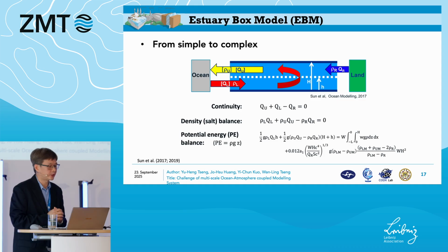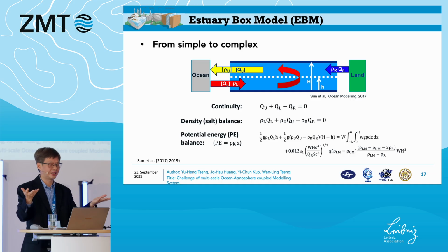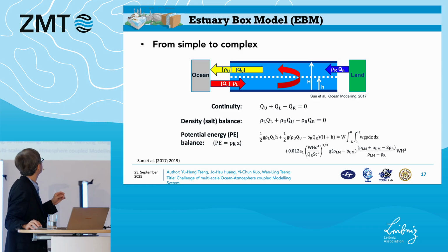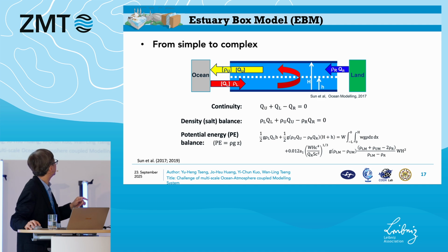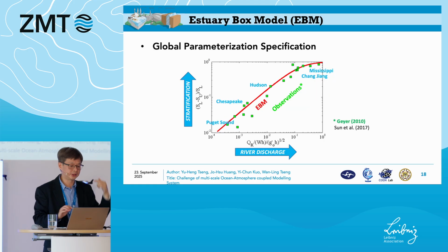So just quickly, a little bit about the estuary box model. We are trying to parameterize, but this parameterization is based on some physics. We consider the continuity equations, the density balance, the potential energy balance, and also the momentum balance within that, so that we can consider the estuary exchange. The open ocean water can move into the land, and the river runoff from the upper layer can move back to the ocean itself.